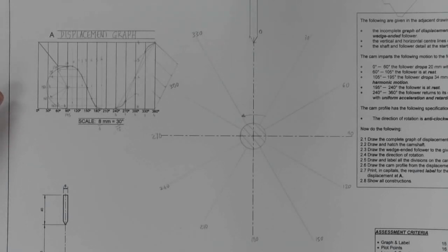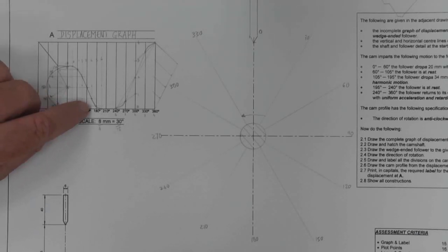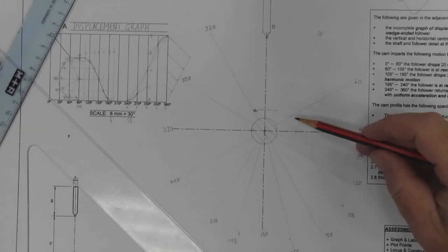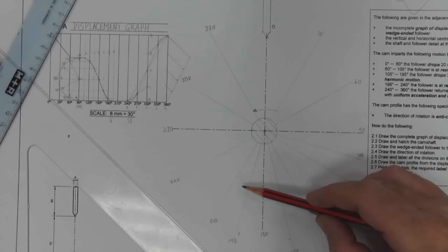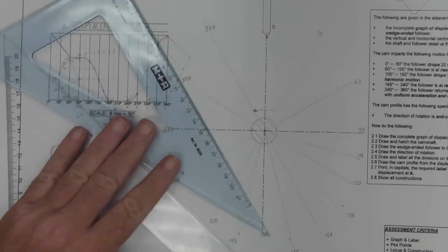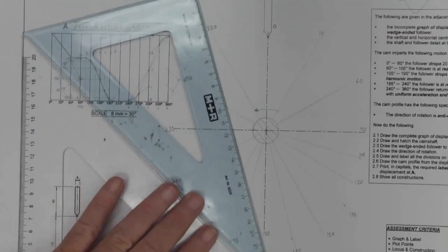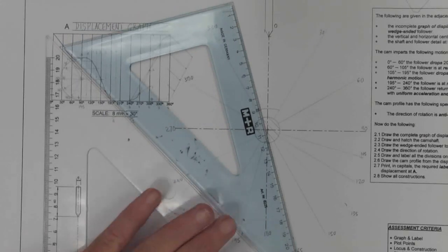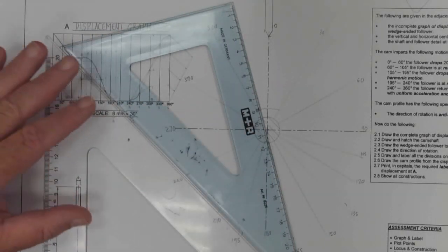Okay, so there we have the labels. I'm going to put in the 15-degree splits that I need to find from 105, 135, and 165. I've put in those extra divisions that I needed here at 15-degree angles. You can use your protractor, or if you work around with your two set squares together, you'll be able to get those 15-degree angles that you need as well.